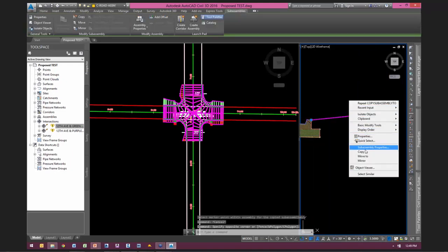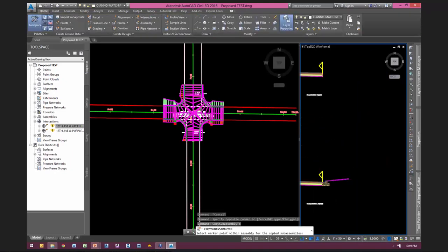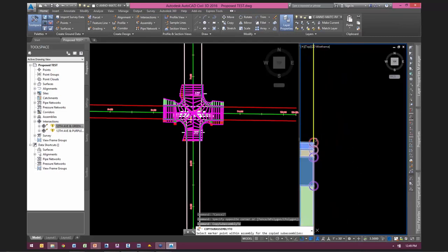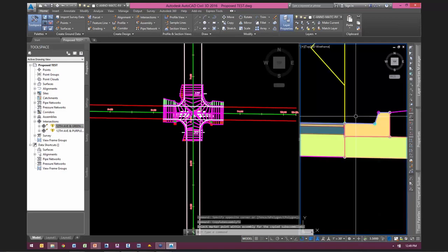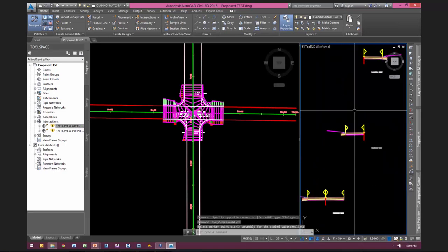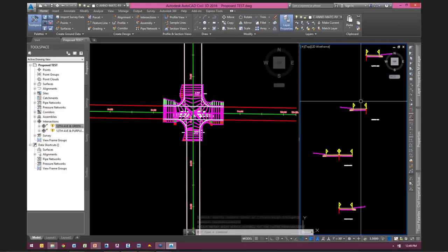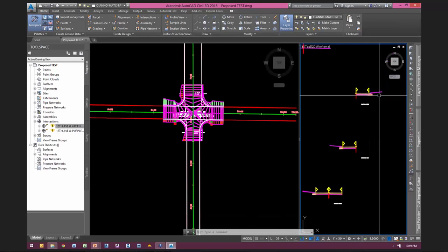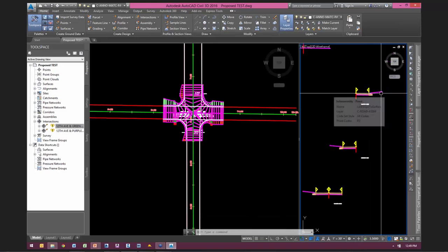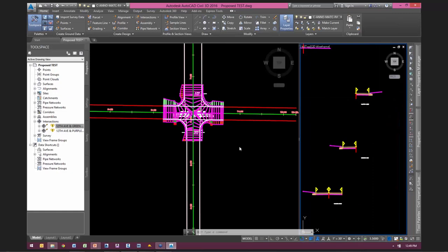Copying the curb and the daylighting subassembly, putting those up here. So granted, we would have potentially sidewalks and a number of other things. If it was a reconstruction, we'd be trying to tie in around right-of-way, a whole lot of other considerations behind the back of curb here, but not the focus of this webinar.